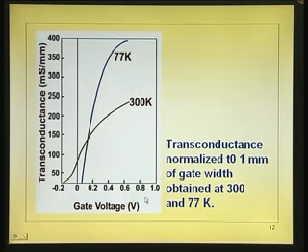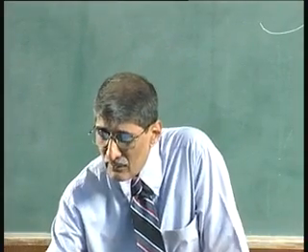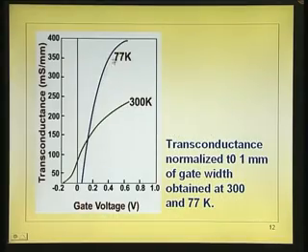One thing that one should note here is, as you go up here to larger and larger voltage, the transconductance increases, okay, because VGS minus VOFF is increasing, number of electrons are increasing. But then afterwards it does not increase that steeply, it gradually tapers off. It tapers off because the mobility of the electrons tends to fall down. In the case of MOSFET also you will see that, because of the high field effects in the vertical direction. Okay. And in this case there is an added effect, that is we are talking of this portion, a slight tapering off.